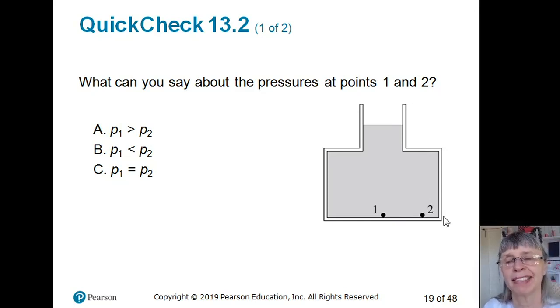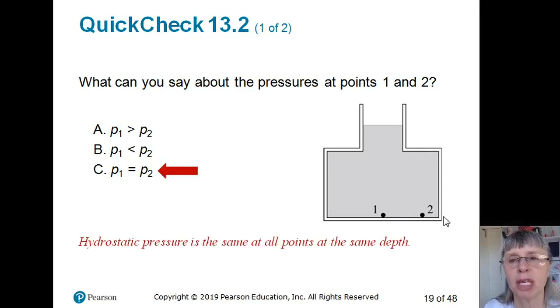What do you think? Yeah, the pressure is equal because there's a horizontal line. If you drew a horizontal line, it would go between both of these. So even though the depth here underneath that closed section looks different, because there's a horizontal line, the pressure of these 2 points is equal. They're at the same depth relative to this open area.